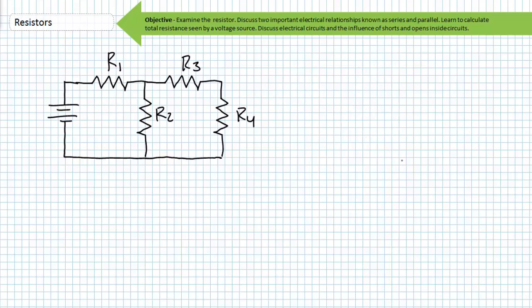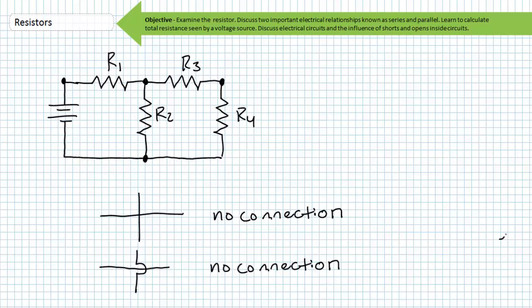If resistors or wires are connected, schematics indicate they're connected by placing a dot at the point of connection. If wires merely pass over or under other wires but do not connect, there will be no dot. Oftentimes you'll see an overpass symbol to indicate passage but no connection. Use this symbol. You'll immediately appreciate the clarity.